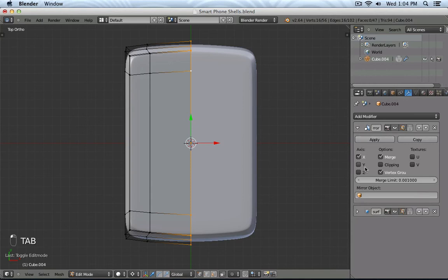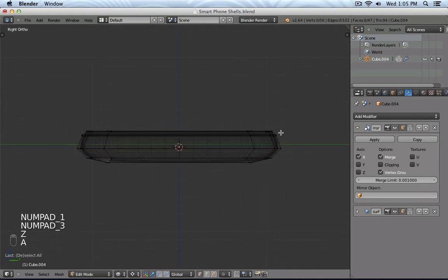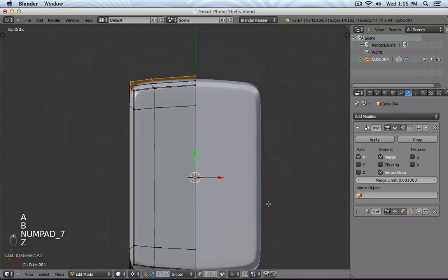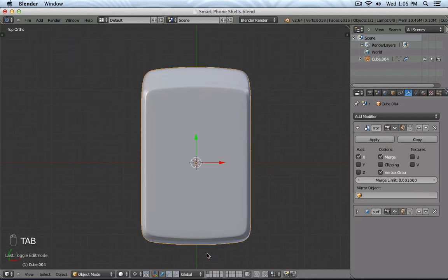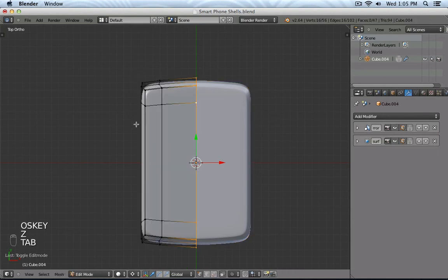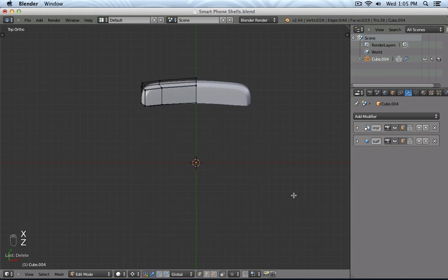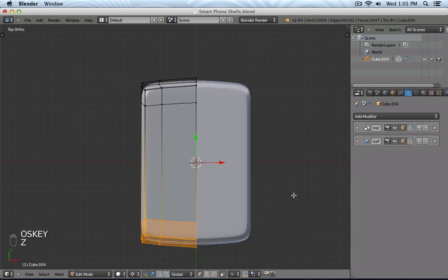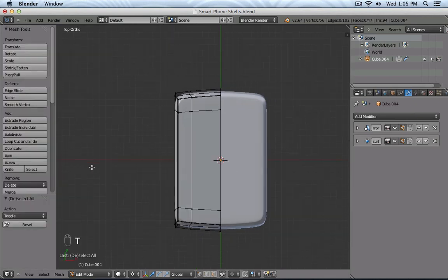Well, let's say you also would like to have the y-axis being possible to be used. Currently, my object or my mesh is built in a way so that, for example, I have only a left to right symmetry, but not a bottom symmetry. So to do this, all I need is just 1/4 of my model. But the problem is, if I select all those points and delete it, I end up with this part. So what I need to do is, right here, I need to add another cross section.